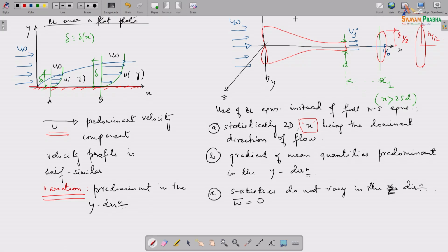So, here there was no flow, I mean this was quiescent, meaning there is no flow happening. Now when the jet comes out, however, there is flow. So where do we stop? Where do we say that the jet is not spreading anymore? Well, this is essentially a region where the velocity is such that it is quiescent. That is how we define what r half is. Okay.